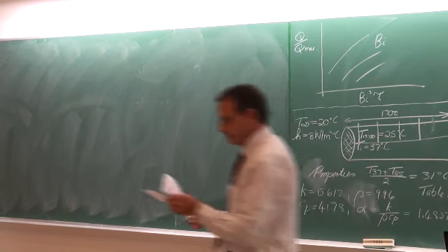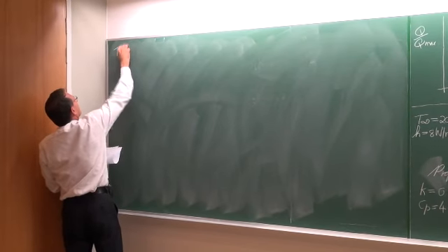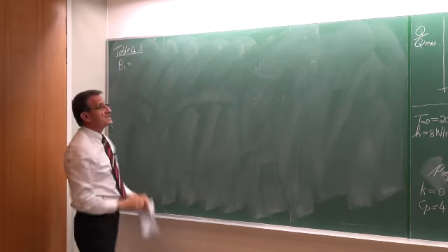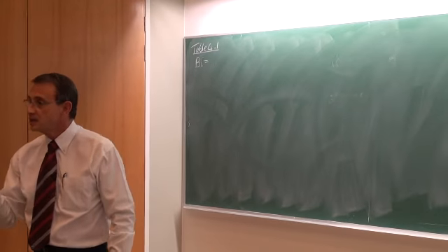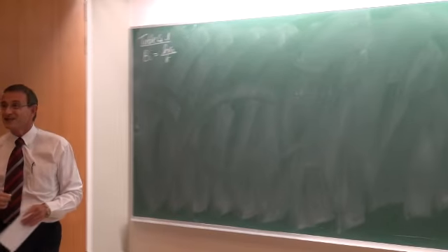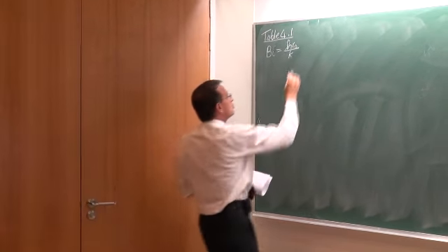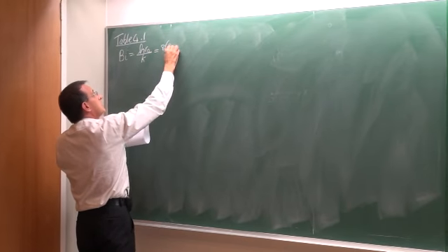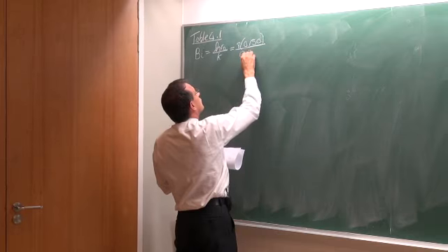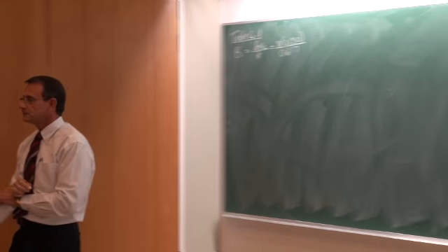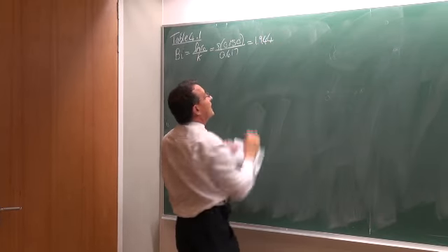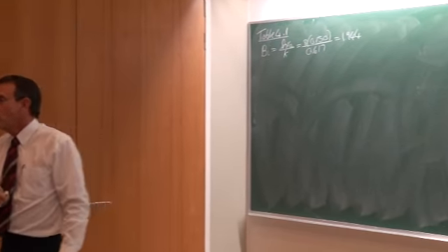If we look at table 4.1, in the fine print, the Biot number for a cylinder is equal to the heat transfer coefficient multiplied by the radius divided by the thermal conductivity K. The heat transfer coefficient is equal to 8. The diameter is equal to 150 millimeters, so it is 0.150 divided by the thermal conductivity, which is equal to 0.617. So the result of that is that the Biot number is equal to 1.944, and that is going to give you other values for lambda and A1.